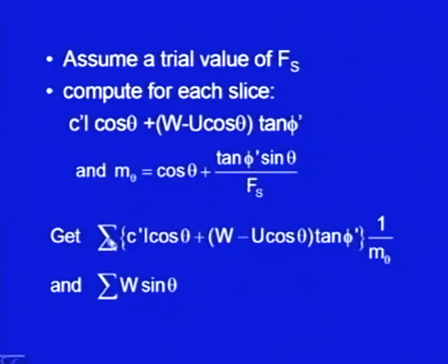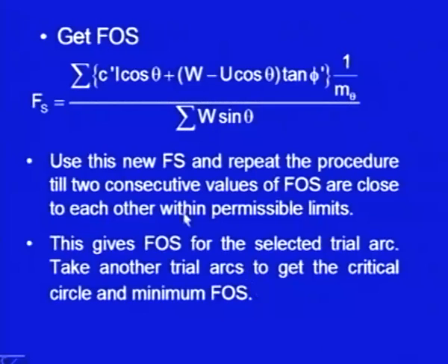the value of this expression which is there in the numerator, summation of C dash L cos theta plus W minus U cos theta tan phi dash, times 1 upon m theta, and also we get this value, summation of W sin theta, which is there in the denominator. Then put it in the factor of safety equation, F s is equal to this numerator divided by denominator.